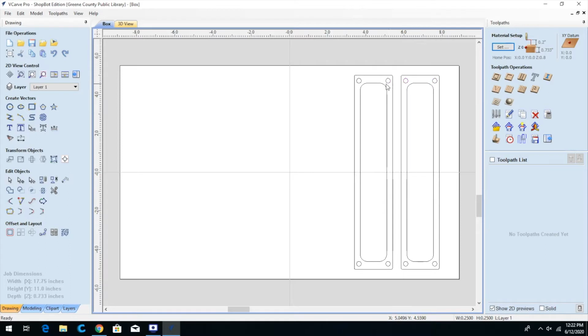When you are creating toolpaths, it makes the most sense for most jobs to start at the lowest cut depth and work your way down. So we will begin with our drilling toolpaths. Click on the outline of each of your circles to select it. Hold Shift to select multiple objects at once. Once all are selected, click the Drilling Toolpaths option.